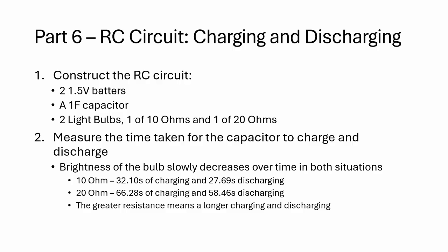There was 32.1 seconds of charging and 27.69 seconds of discharging for the 10 ohm, and for the 20 ohm it was 66.28 seconds of charging and 58.4 seconds of discharging. The greater the resistance means the longer the charging and discharging.